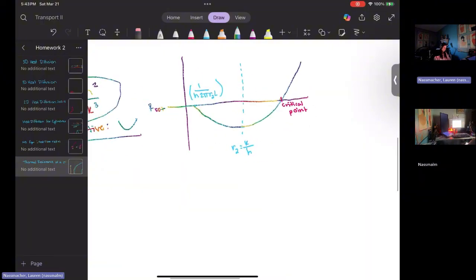And clearly, as R2 increases, there's a point in the graph that tells us that we're not adding enough insulation to where it's actually decreasing the effectiveness of the pipe. And then there's a critical point which shows us exactly where the insulation is perfectly working and it's very ideal, and that's what you're looking for in a real world scenario.